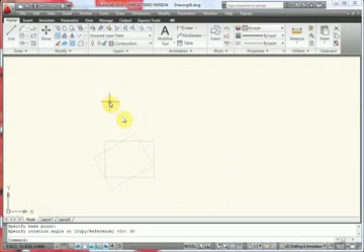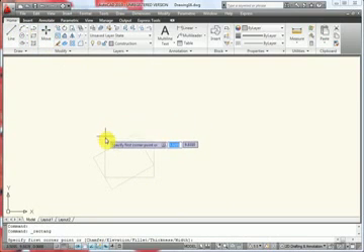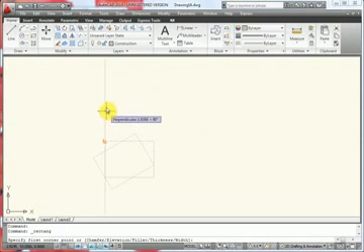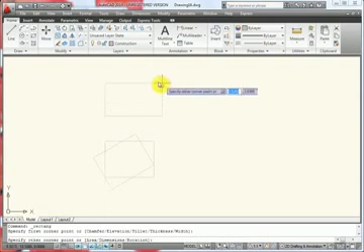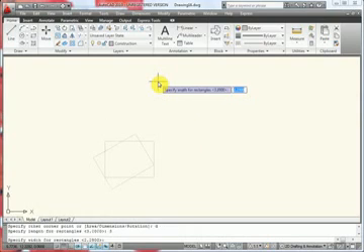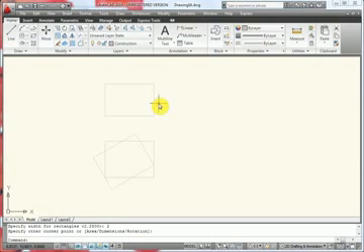I'm now going to draw a rectangle above it, which is going to represent the top view. So I'm going to choose the rectangle command, and I'm going to use object tracking, which is by bringing my cursor over this corner right here, it's going to render a dashed line that I can use to reference perpendicular from this point right here. Using the dynamic input window, I can roughly estimate 1.5 inches away from that. I'm now going to enter D on the keyboard so I can give this rectangle dimensions of 3 spacebar, 2 spacebar. Left click to end the command.